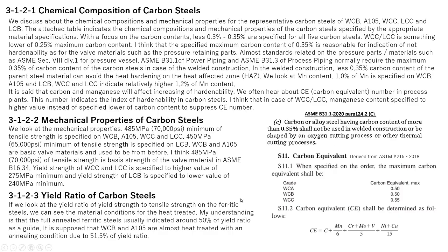So we have to purchase the related material from the supplier with the special specification of carbon equivalent 0.43% maximum to be controlled like this.